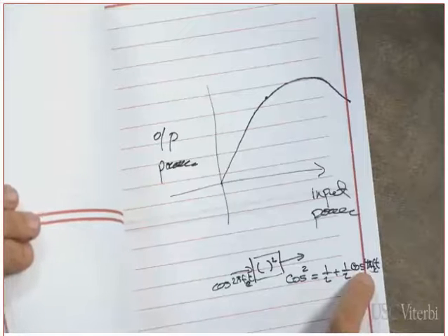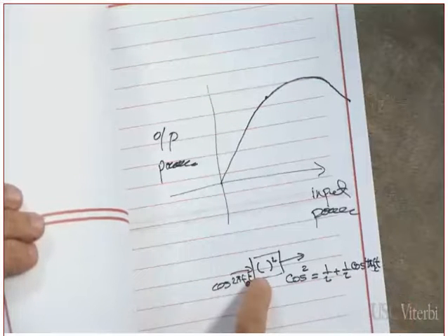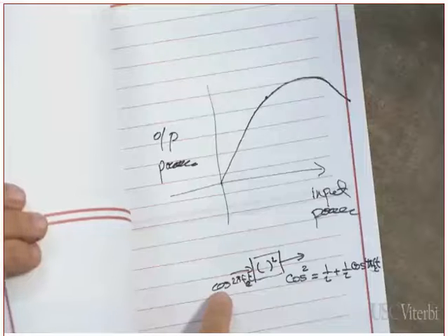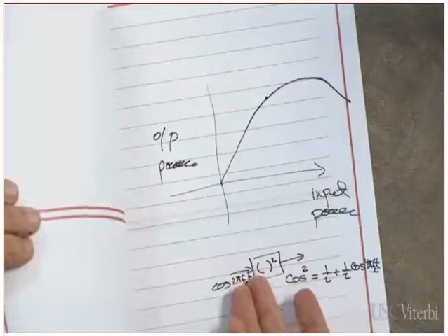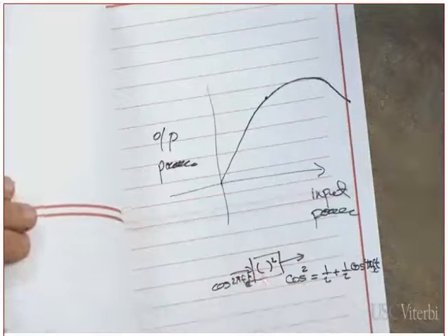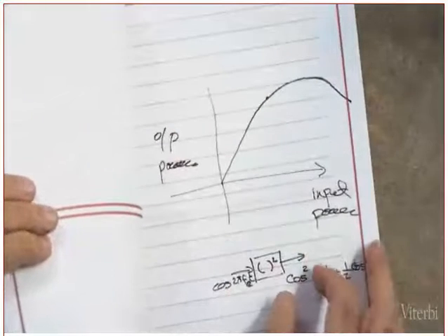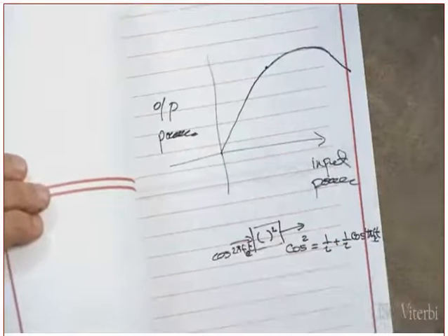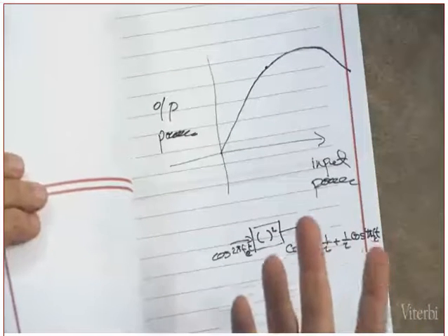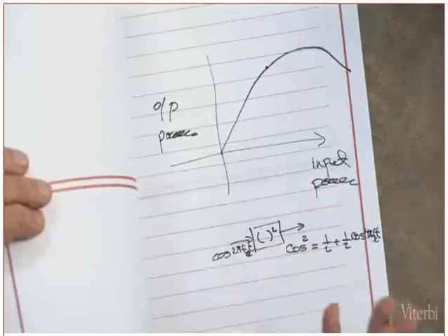You might say, Professor, but this is just the second harmonic. It's not a side lobe. But you have to remember, the input to the square law device is not a pure carrier. This is a pure carrier. In reality, the input to the amplifier, to the nonlinear device, is a carrier modulated by the information. Yes or no? Are you following me, or are you losing me? You are not transmitting only one carrier signal with no information. Clear?